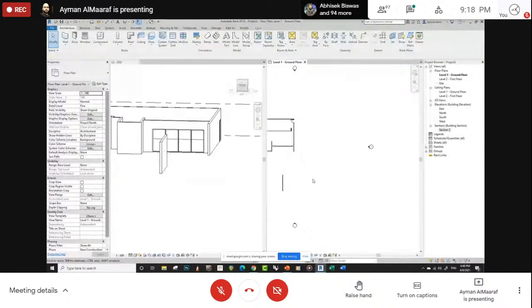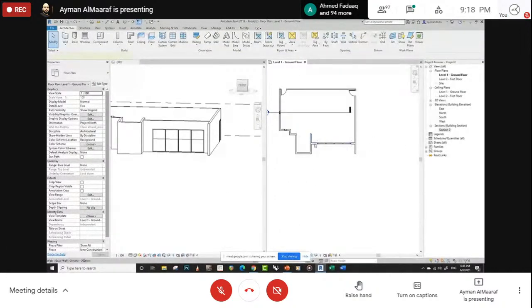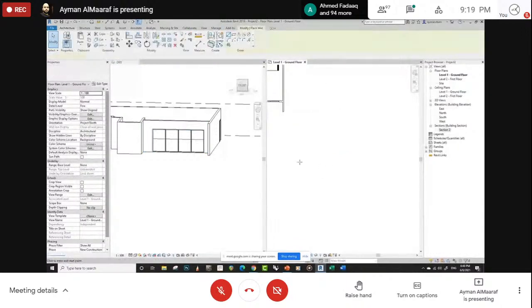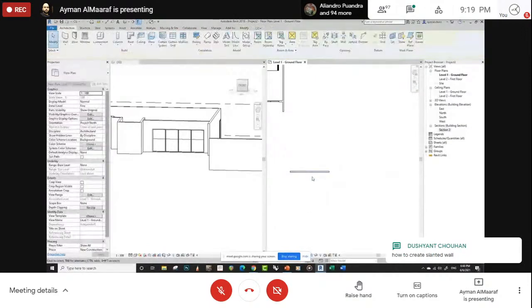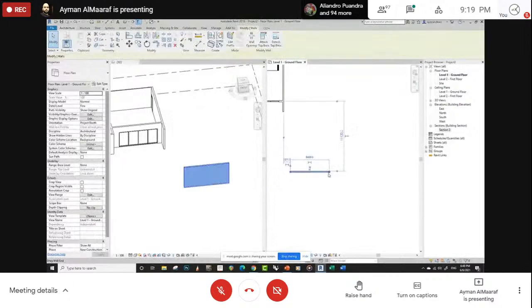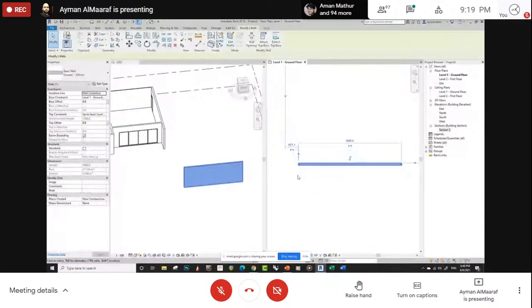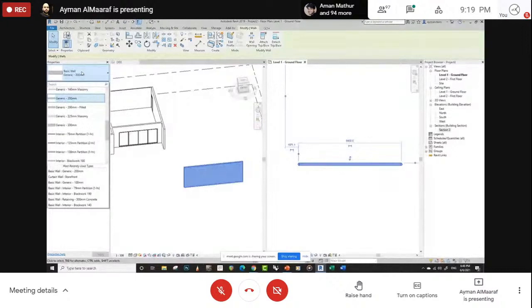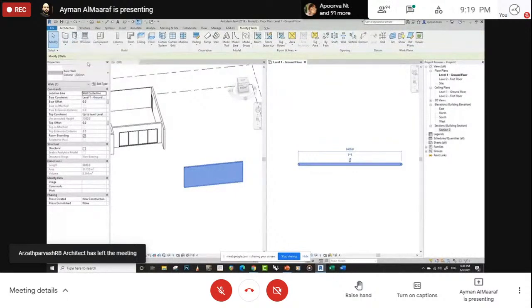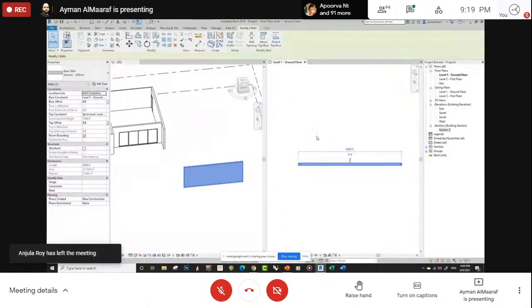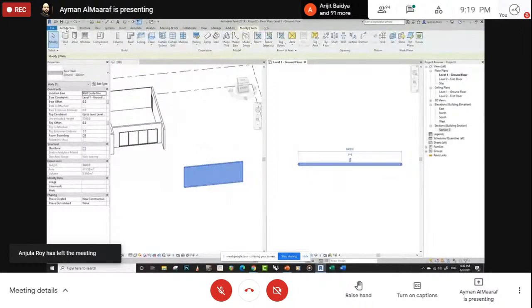Now, you said you wanted to discuss the curtain wall again. So if I draw a wall right here, go to architecture wall and click from left to right. This is a basic wall. So do you remember we talked about the hierarchy of Revit? So we have door, you have the different sizes of the door, you have all the instances of the door inside your model. So for the walls, the classification, the first thing is the category, it's called wall.